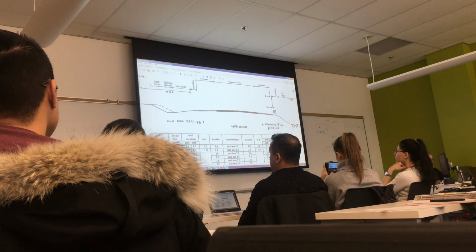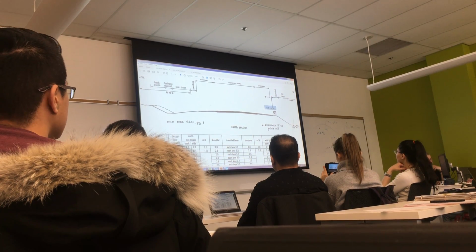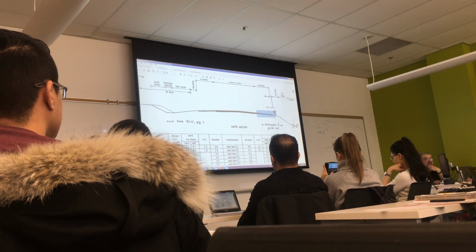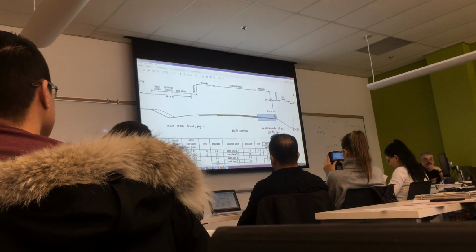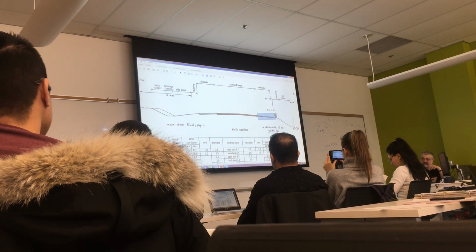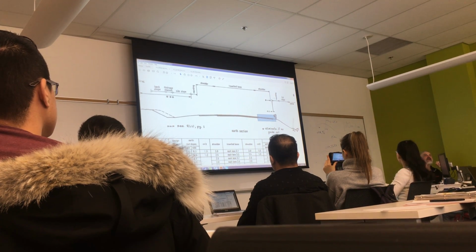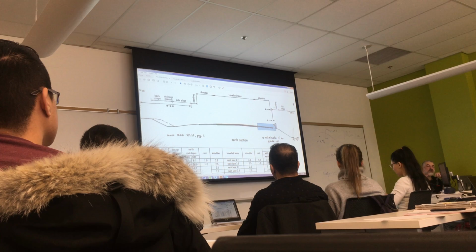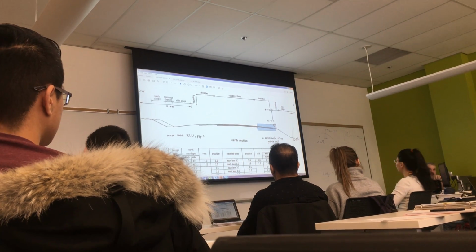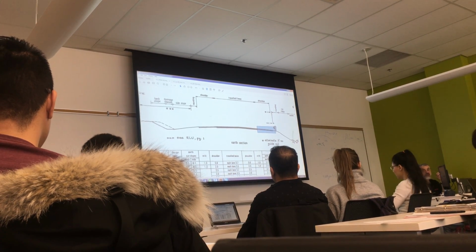If I had a guide rail, I would need an extra ½ meter on the 6% plane between the shoulder and the rounding. I need a little bit of room. But that's beyond today's discussion. To draw it without a guide rail, and then we'll analyze whether you should put one in there.